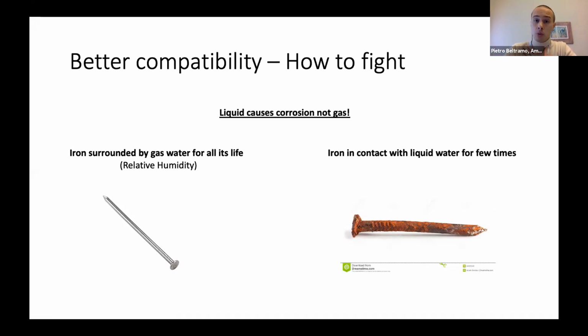The point is, if I have to make a choice, I would try to keep everything in gas phase as long as I can. Of course, as I told you before, I want to be politically correct and not push too much on one technology or the other. If you don't control the relative humidity properly, you condense 35% H2O2.